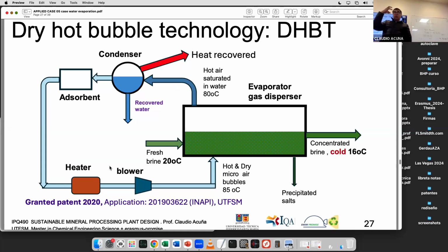So you have a stream with very high enthalpy. We were playing around with Eduardo with a balance with enthalpy to put the numbers. It's not the same having dry air in terms of energy, or having 80 degree hot air, or having 80 degree hot air with 90% humidity. 90% humidity has a lot of energy, enthalpy accumulated, because of this lambda.